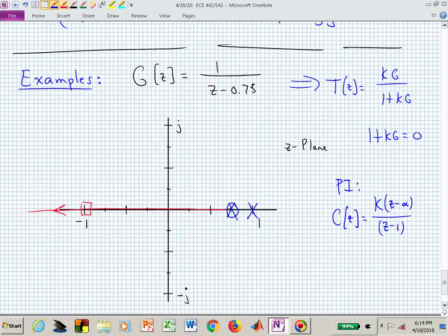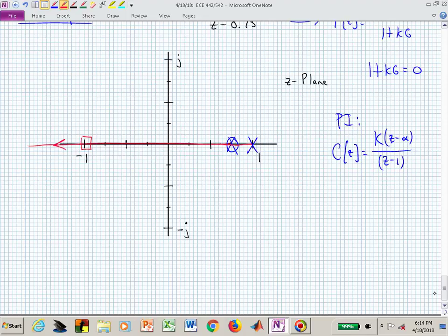The root locus now has the exact same structure as it had before, except now you have that piece. And now you're guaranteed of having 0 error due to a constant input because you've located a pole at z equal to 1. So now how do you pick the K?